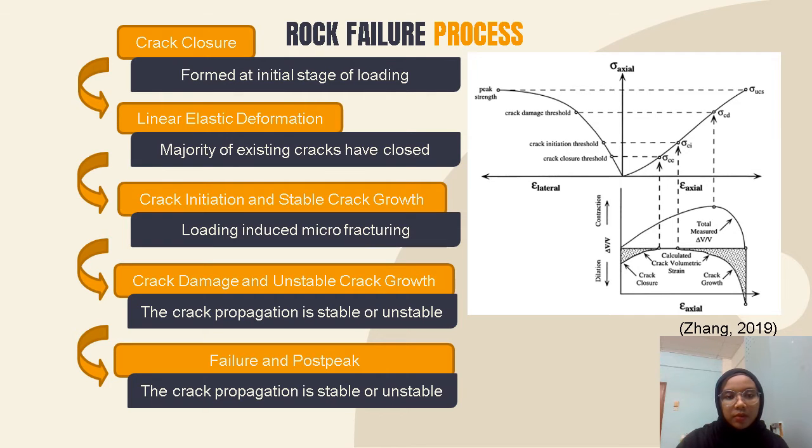Next, we'll move on to the rock failure process. There are a few processes that lead to rock failure. Firstly, it will undergo the crack closure phase, which starts to form at the initial stage of loading. After that, linear elastic deformation takes place, in which the majority of the cracks have been closed after the stress is subjected.